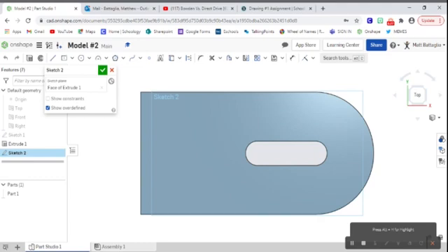And looking at my model, looking at my drawing, I know that this is a 4 inch by 1 inch rectangle, and these rectangles are shown on both sides. So I'll start by selecting a corner rectangle, and I'll go on this back edge here. You see I get my orange square and circle, and I click. I will drag it out. And I know, as I mentioned, this is 4 by 1. So now I have a 4 inch by 1 inch rectangle over here.